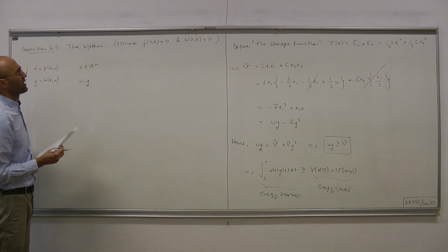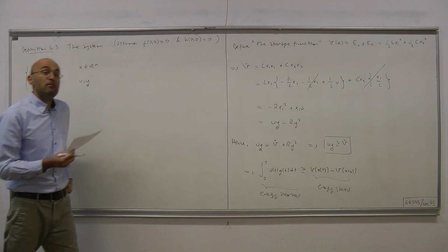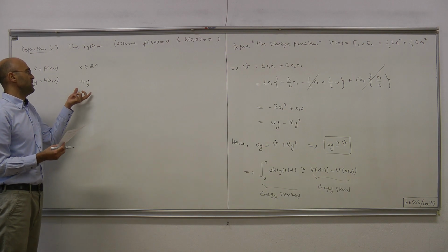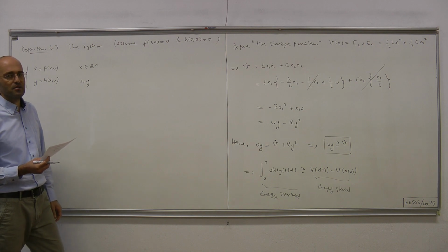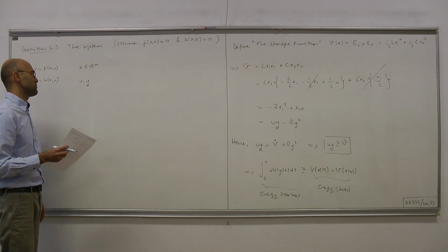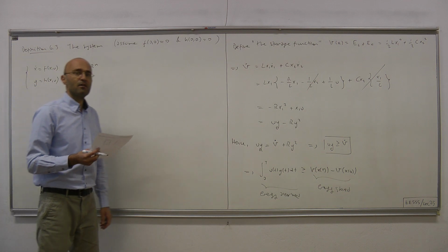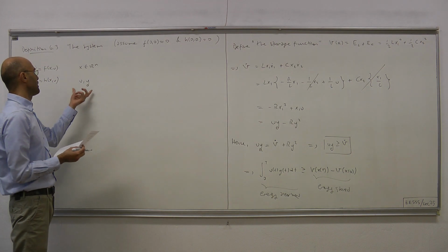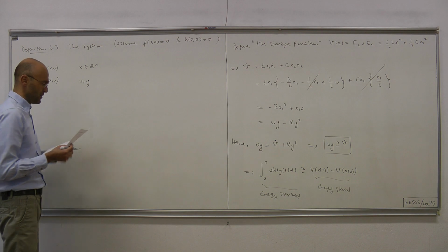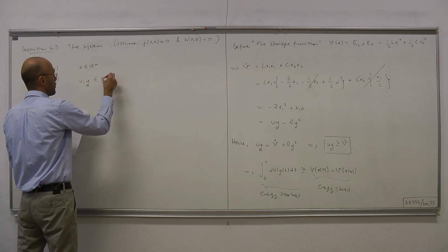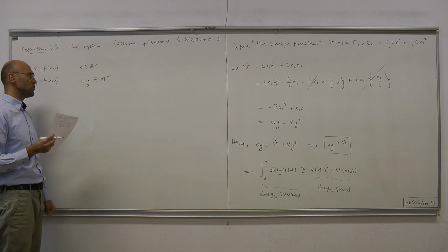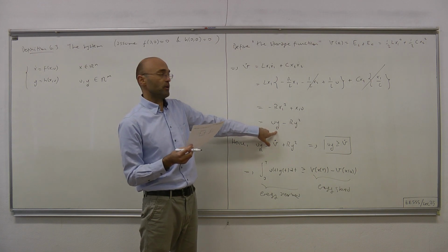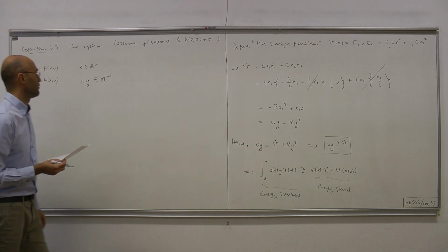Okay, so this is one of the key properties, maybe you can call it a restriction of passivity. So it's applicable only to systems where the input and output are of the same size. Okay, so it sounds like a very narrow class of systems, but there are many, many important physical systems and applications in engineering that it's worthwhile to study this seemingly restrictive case. Okay, u and y, they belong to R^m. They are of the same size. So that the inner product, this product, we will generalize to the product when u and y are vectors, the inner product is meaningful.